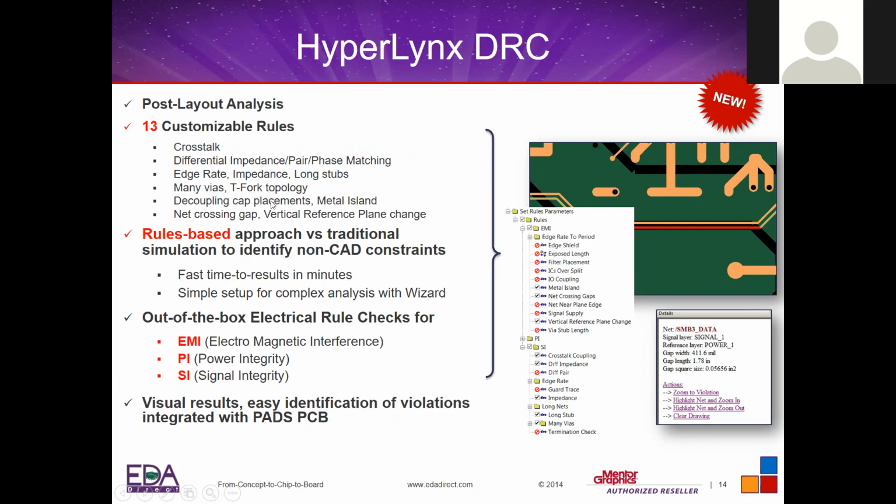And the coupling cap placement, for example, it's best to be close to the chip, but sometimes due to whatever constraints the customer has, or maybe they focused on signal integrity, signal routing, and don't think about power integrity, capacitor placement. And so once it's routed, now you're trying to put down capacitors and you don't have room. And now those capacitors are further away from the chip, which lessens their ability to function as filters for these rails. So we check for that kind of thing.